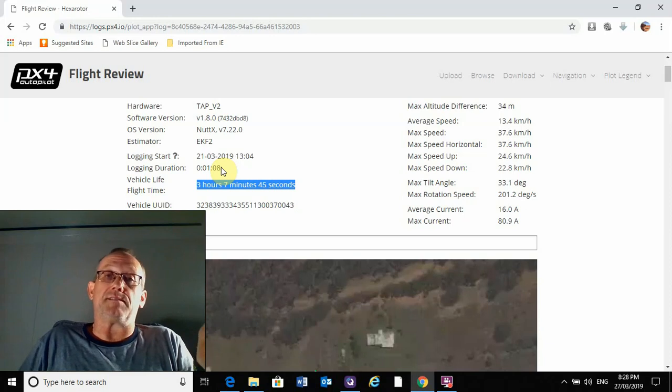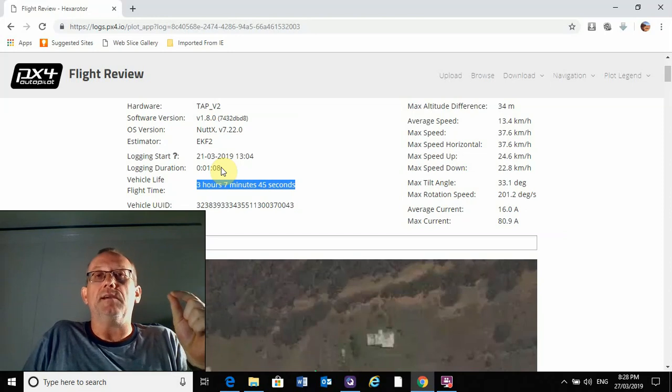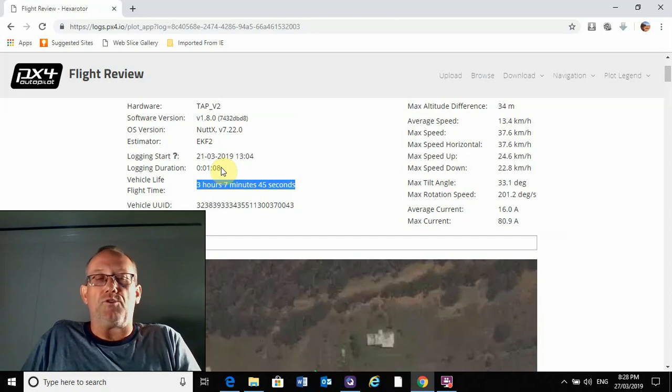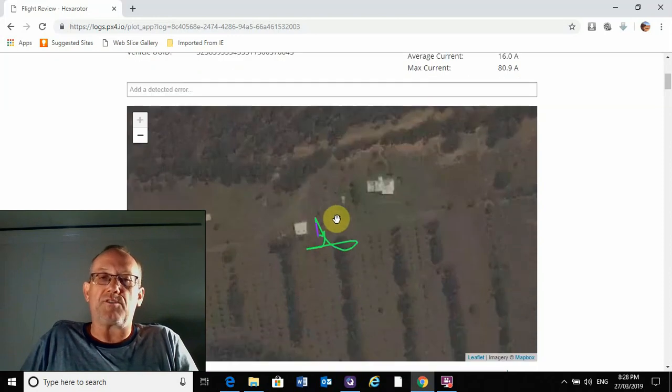And if there was an accident, look, I calibrated, I did everything I was meant to do. So enabling that in the settings, to start the log even if you don't arm the motors, will increase the file size, but it gives you that bit more surety, allowing other people to know exactly what you did. All right, so let's scroll down here.